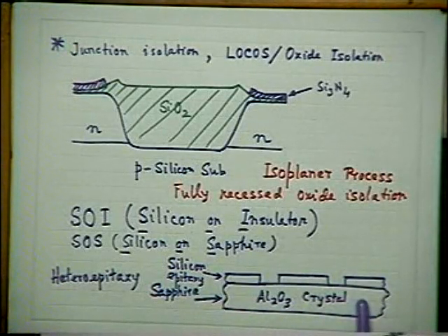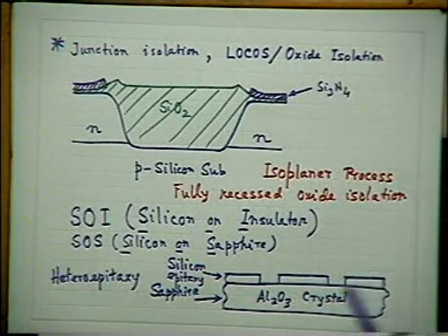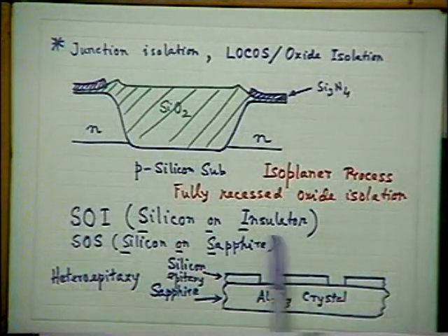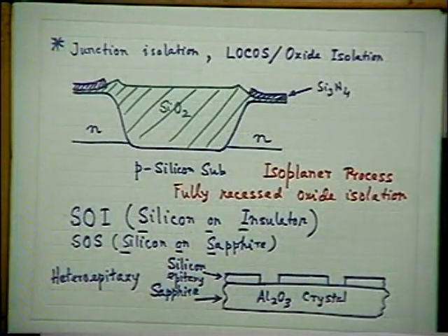And because the bottom material is an insulator, you don't have much problem, because even if there are some electron holes generated in the insulator, they are not available in the semiconductor. Whereas on the other hand, if you do not have such alumina crystal in the bottom, and the entire thing is silicon, the radiation penetrates to the bottom, and a lot of electron hole pairs are generated, which affects the circuit operation, and more damage is created, as well as radiation-induced currents and other bad things. In the insulating case, these cannot occur.